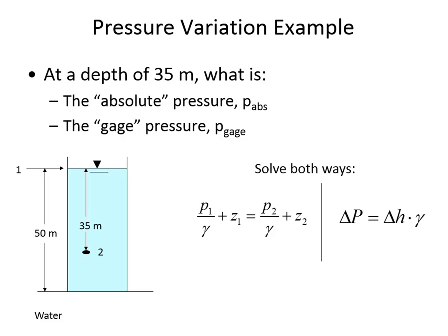And the way that we applied that hydrostatic equation was by looking at a tank of water where an invisible triangle was floating just above the water surface to indicate that it's in contact with the air. And there are these little invisible lines indicating the water ripples, reinforcing the fact that it's in contact with the air. And what that means is that if the air pressure is 101.325 kilopascals relative to the vacuum of space, then the water pressure right there is the same.